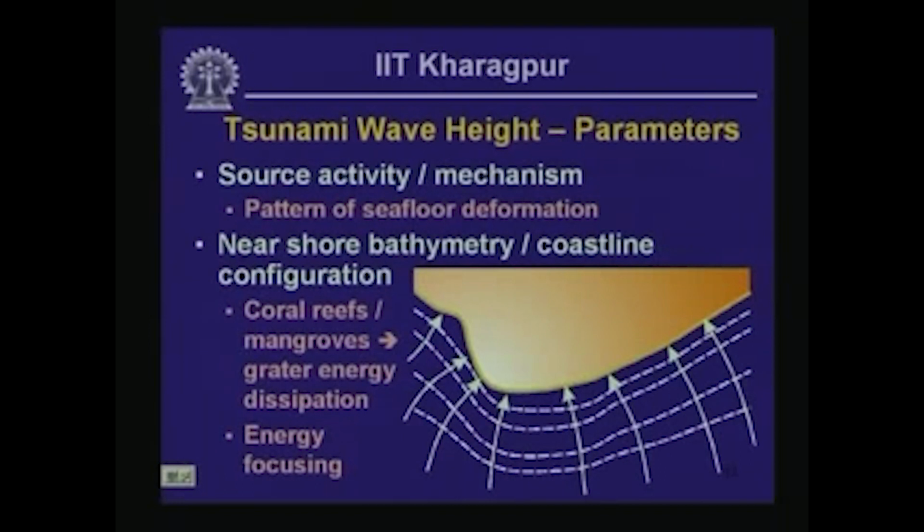In other words, whether the waves are generated by an underwater landslide, by reverse faulting, or by normal faulting. What is important in this case is the pattern of seafloor deformation and how the deformation is propagating in a certain direction along the seafloor. So these are paramount considerations in estimating tsunami wave height.